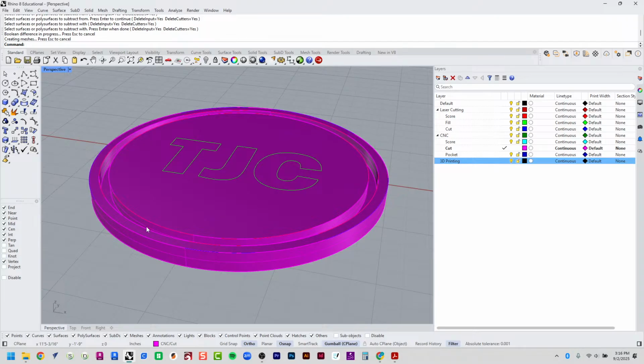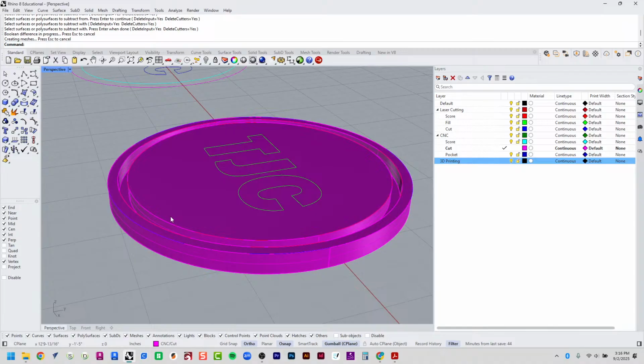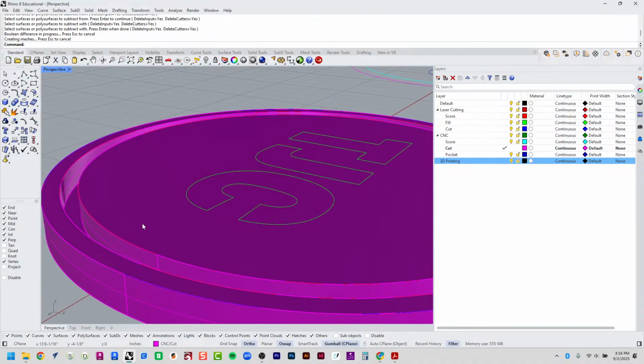And now you can really see what it does, right? It takes two solid polysurfaces, and wherever they coexist, I can say, hey, wherever they share that area, get it out of the main one. So the from was the big 4-inch circle, quarter-inch thick. The with was those inner two circles, 3/16 of an inch thick. Does that make sense? I subtracted B from A, with A being the big one, B being the smaller offset inside of it.